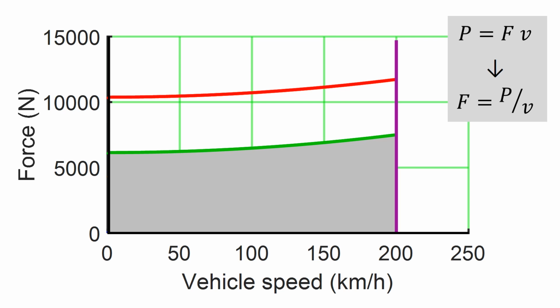It is interesting to plot curves where each point on a curve gives the same power value to see what operating points require high or low power. Since traction power equals traction force times speed, the force along these curves equals the power divided by the speed.